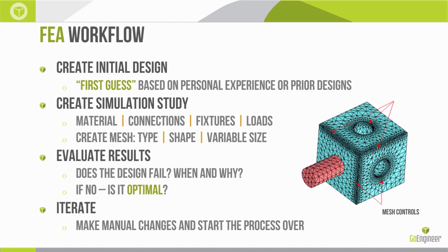So I'm setting up boundary conditions, and then I'm also creating a mesh. Creation of the mesh can be an automated step. There are tools to do that, but it's usually something that me as the person setting up the study wants to have some involvement in. The results of my study are only as good as the boundary conditions, the accuracy of them, but also my mesh.